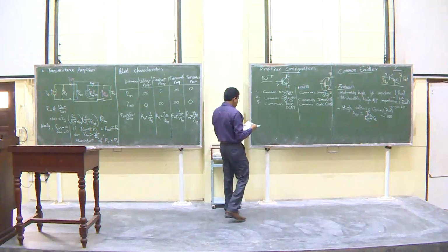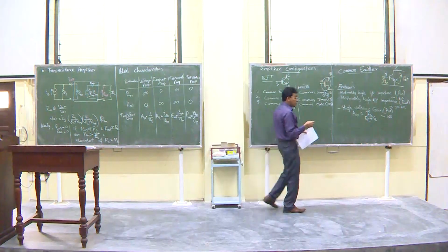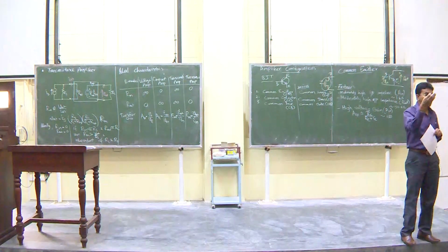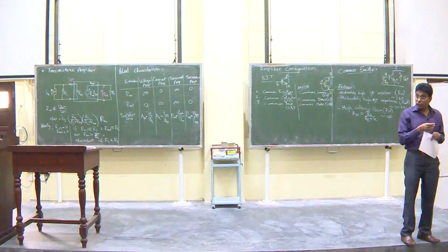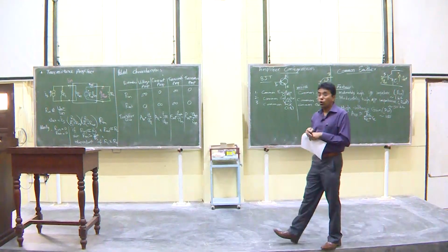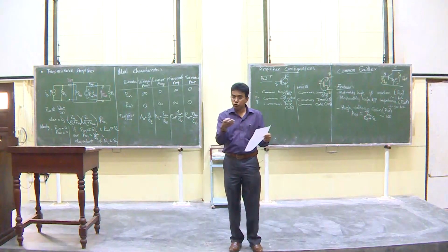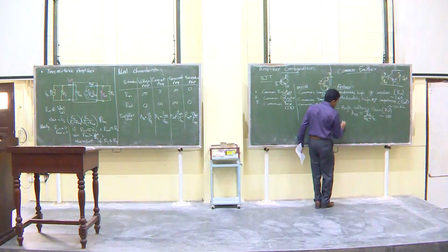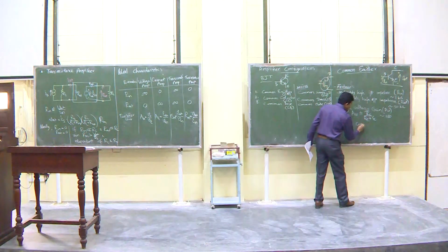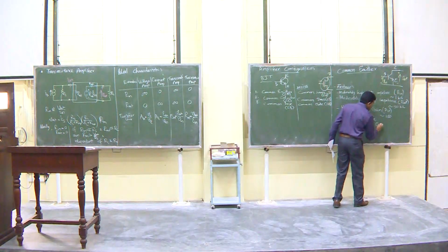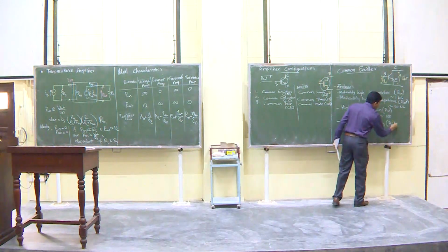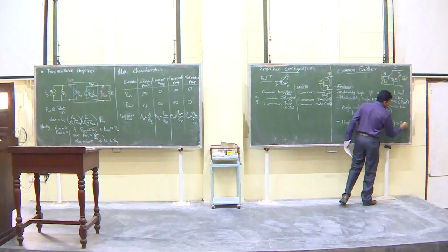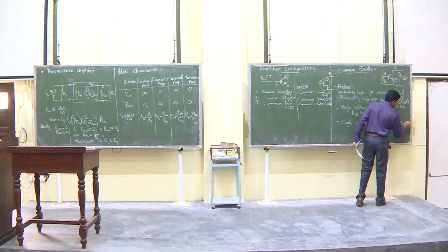In addition to that, input current is IB. Output current is beta times IB, IC. IC is the output current. So again, current gain is also quite high, which is equal to the beta, in the range of 50 to 100, right? High current gain. So AI is roughly equal to beta, which is in the range of 50 to 100, let us say 100.